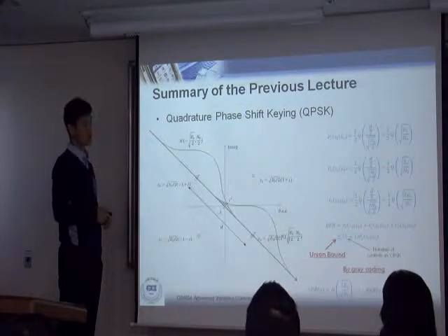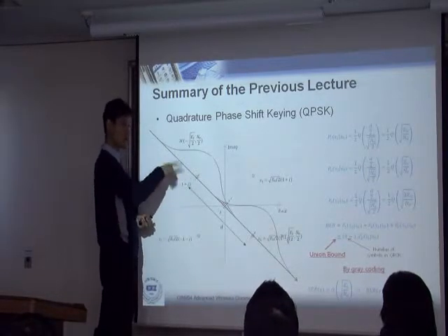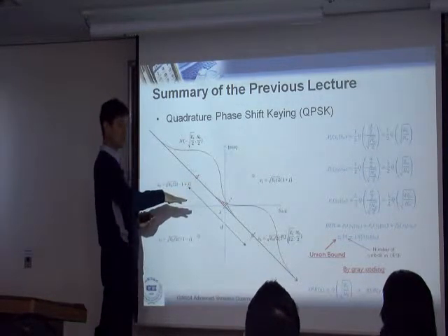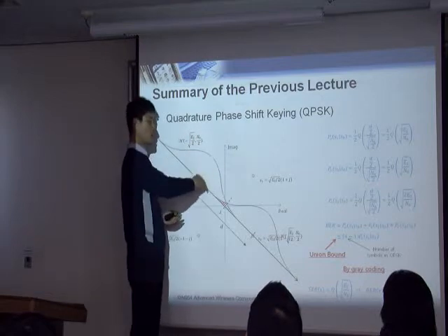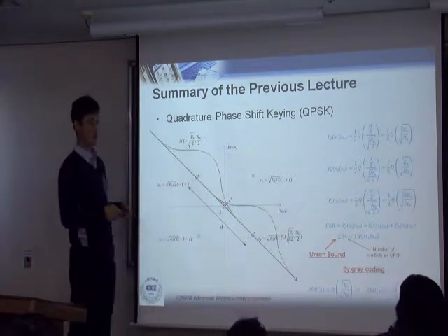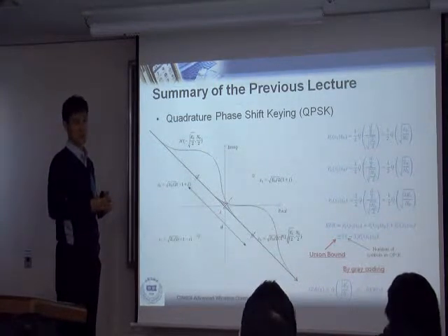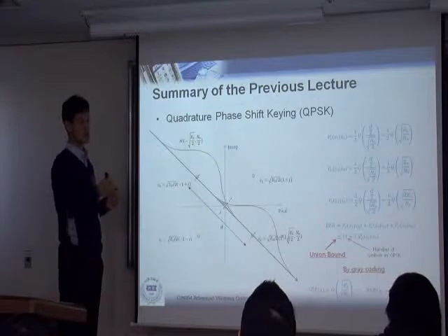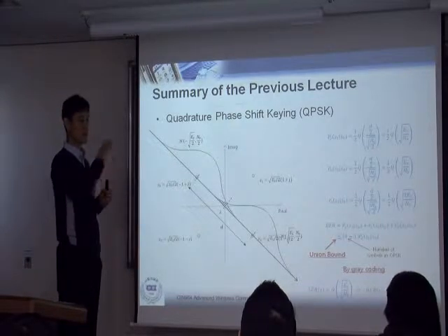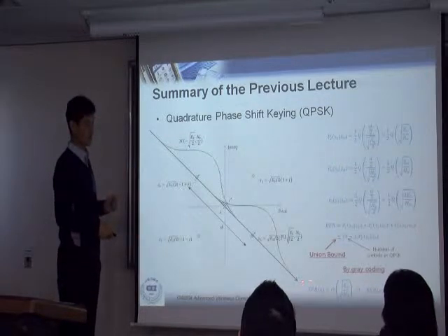So if you draw, let's say, a waterfall curve like BER versus SNR, and we also draw the SER, symbol error rate, versus SNR, how can you compare? Is it going to be the same? For BPSK, both will be the same, right? In fact, for BPSK, there's no separate symbol error rate.